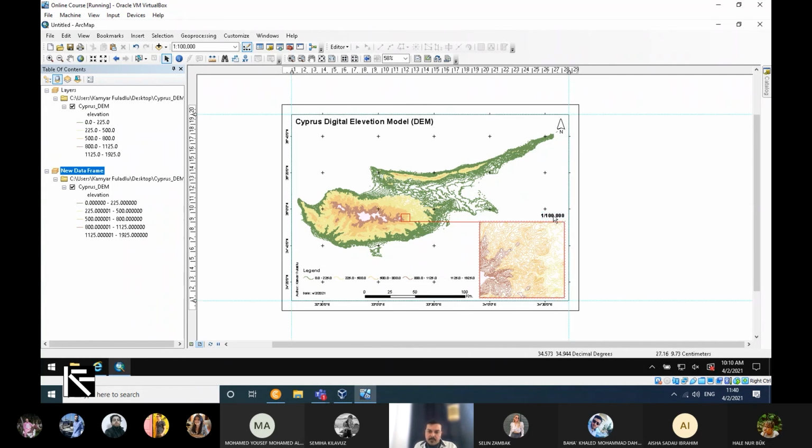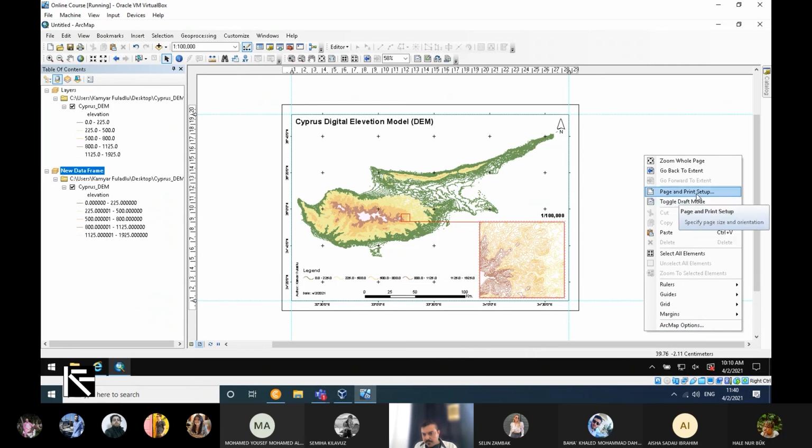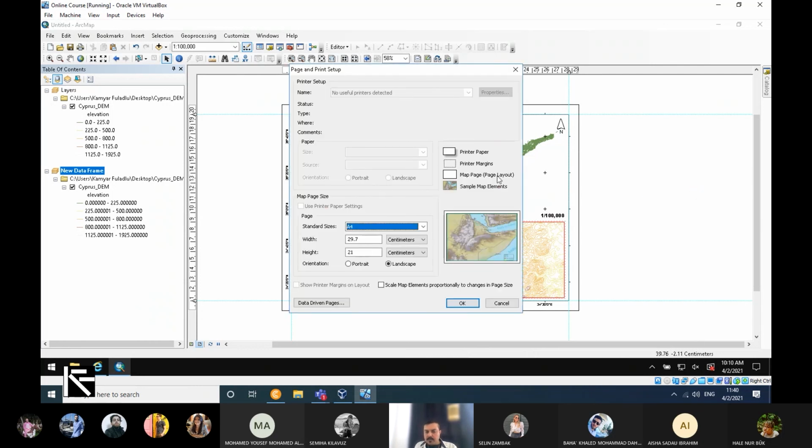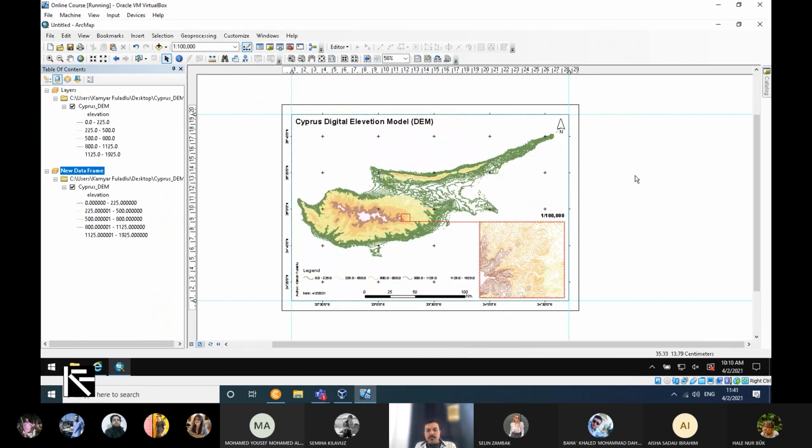If you use this one, you remember that my page size was A4, as you can see here. But if I go to, let's say, the stationery and take a printout on A3, it means that my scale almost changed. It becomes twice bigger than the reality. But this number does not change. It is fixed and writes 1 over 100,000, which is wrong.